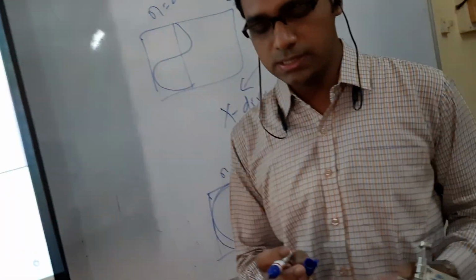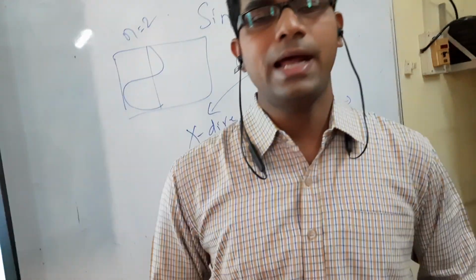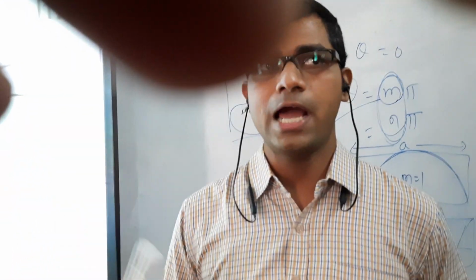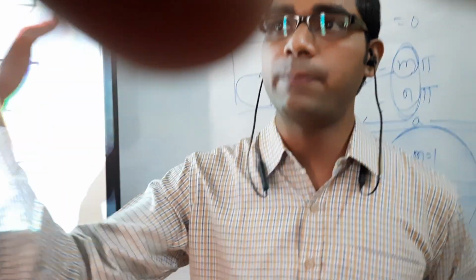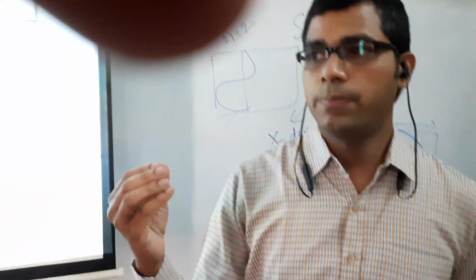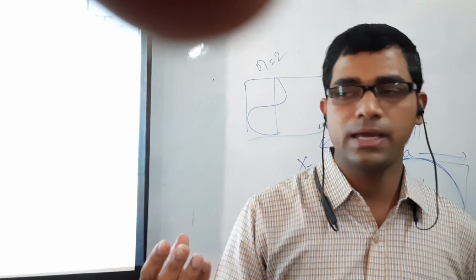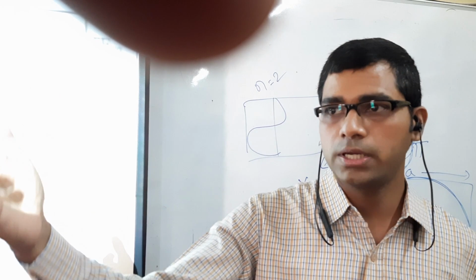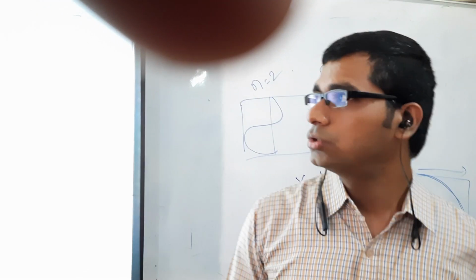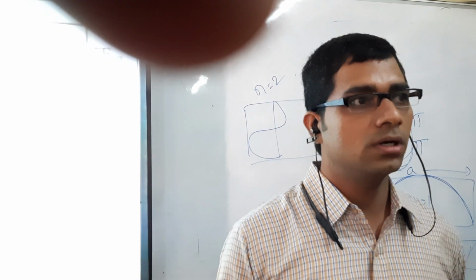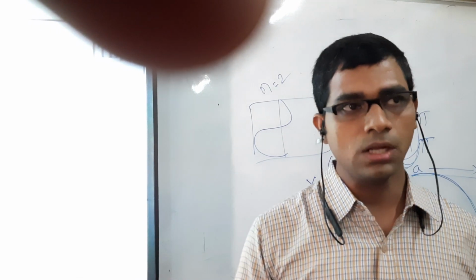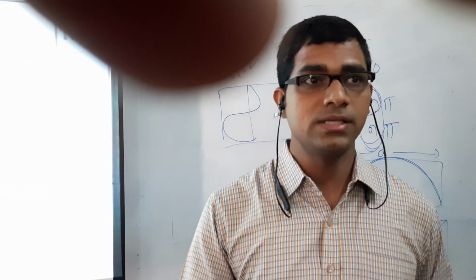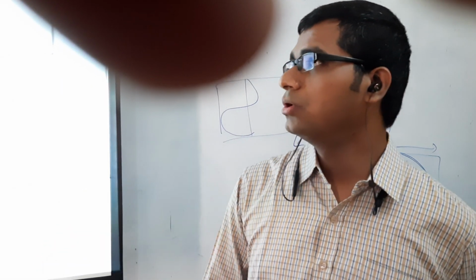But what is a cutoff frequency? A rectangular waveguide acts as a high pass filter. High pass filter means it allows the high frequency. From one frequency onwards it passes. Suppose the cutoff frequency is 1 gigahertz. That means from 1 gigahertz onwards it passes: 1 gigahertz, 2 gigahertz, 3 gigahertz, 4 gigahertz, like that. So depending upon the cutoff frequency, we have the dominant mode. The mode which has the lowest cutoff frequency is called the dominant mode.